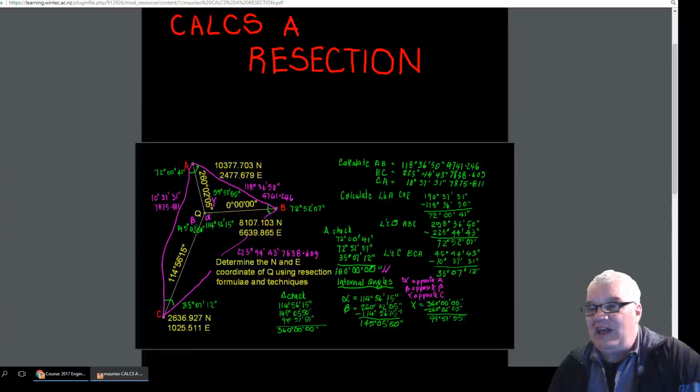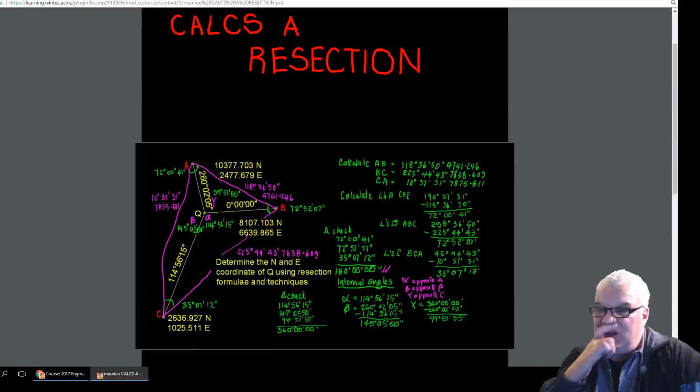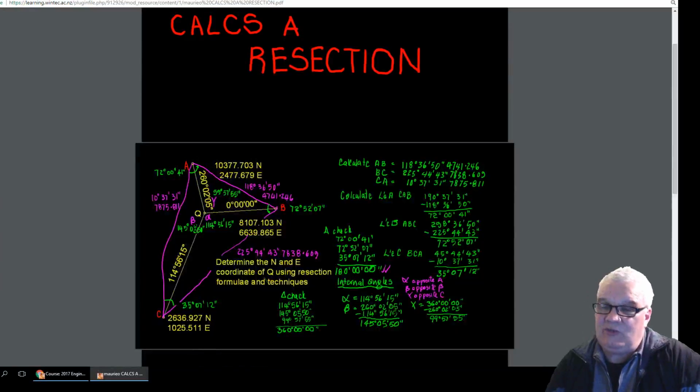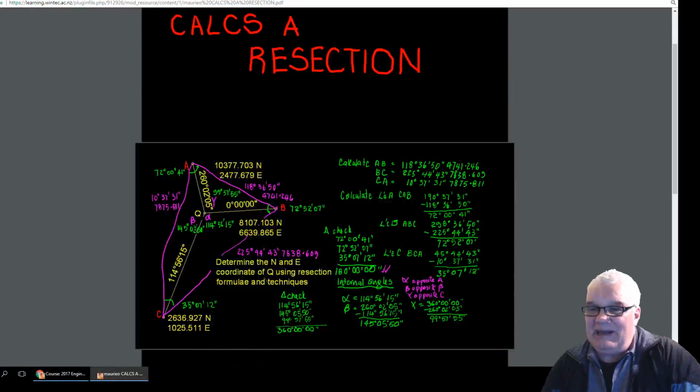So what we did have, and you will have seen them on the hilltops, and that was trig stations or beacons. And so if we were to take 3 of those beacons and set up anywhere and just measure the angles, remembering that we couldn't measure the distances, just measuring the angles, 3 angles, from that information, we were able to work out our position and our bearings.